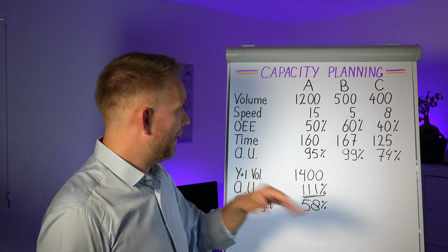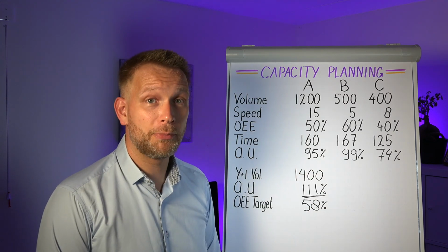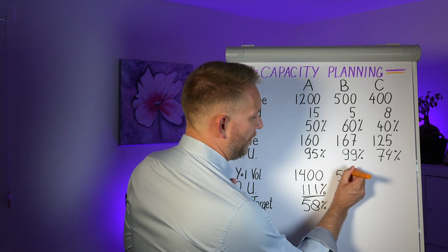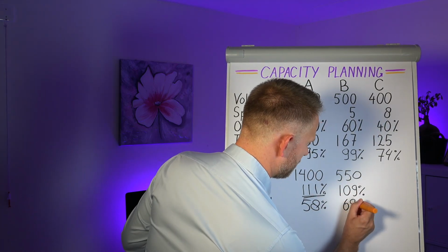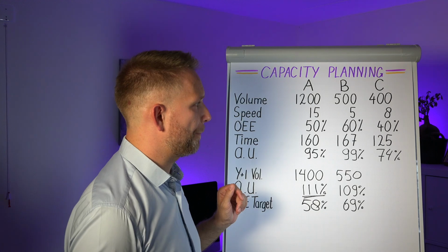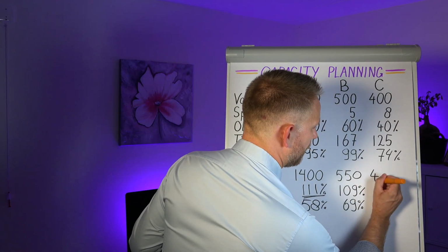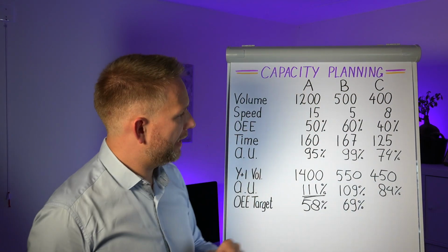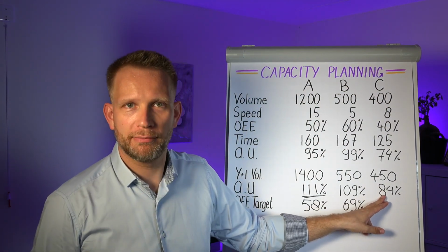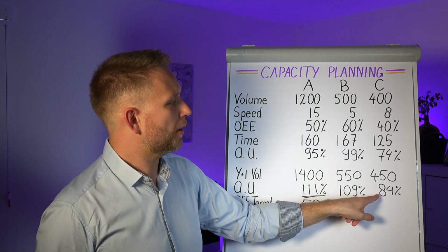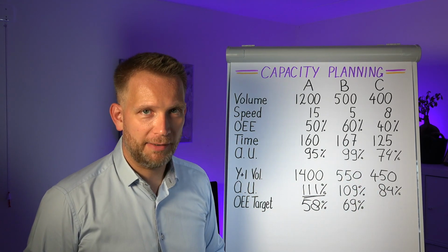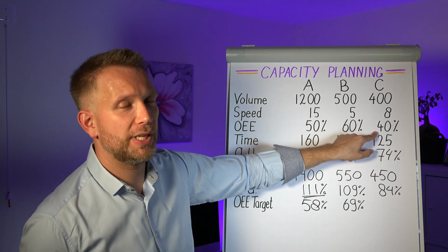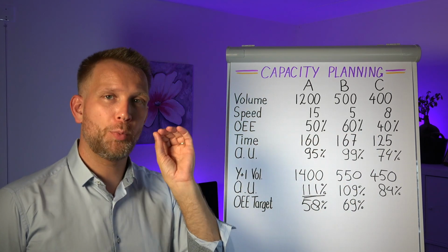Now, some of the other scenarios. So line B should already be improving OEE. But if they also get a 10% bump in volume prediction, they will also need a higher OEE. And on line C, right now we have the capacity. If that gets a good 10% extra volume, well, we actually still don't reach 95. So here, we're not going to say, well, 35% OEE would be enough. No, for this situation, we stick to the current OEE. We're not going to go backwards in efficiency, but this is the OEE target that we need for capacity.